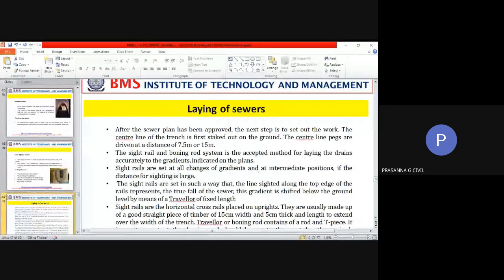So the best way, let us think about a layout now. From a layout, all the wastewater coming from the lateral sewers that you are laying should be able to reach a branch sewer. Let us talk only about that part now. So all the water from each individual building will enter into a lateral pipe, and there will be so many such lateral pipes getting connected, and all these pipes should be leading to a branch sewer.